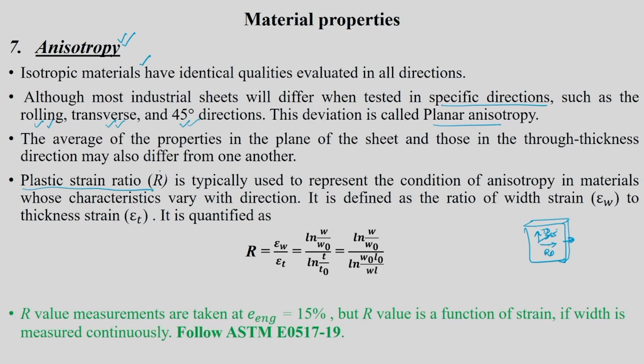So, how do you define this R? It is generally referred to as capital R, or sometimes small r also. R, or the plastic strain ratio, is defined as the ratio of width strain to thickness strain.